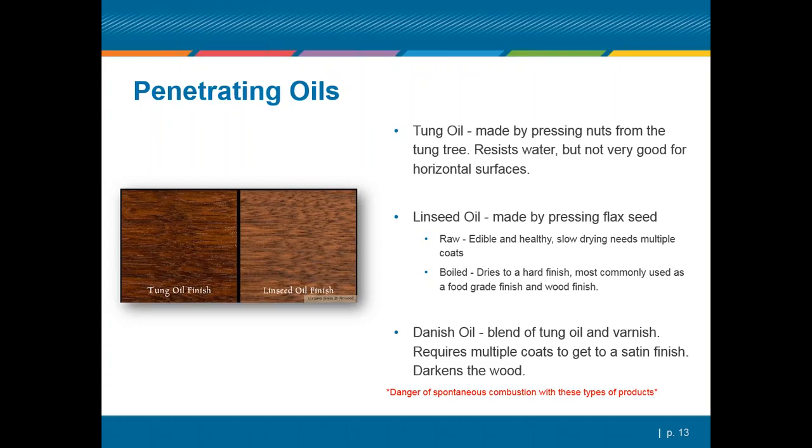These spontaneous combustion issues do occur, so be very careful with the way that you dispose of any kind of rags. Or on a commercial project, if you're specifying any of these kinds of finishes, make sure that the rags are being handled properly on site so that they do not create a fire hazard.